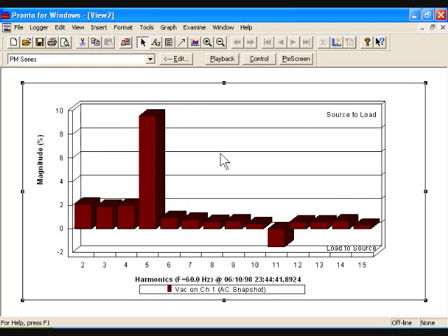And this is a very powerful tool here, because if you have a customer complaint that states, well, I'm getting a lot of harmonics, or my motor manufacturer said I'm getting a lot of harmonics, you can go up to the service coming to the building, measure and do a waveform capture, and then see. Most of the harmonics, if they're current harmonics especially, are going to be coming from the load, because most people cause their own harmonics problems. The power company typically does not generate harmonics.